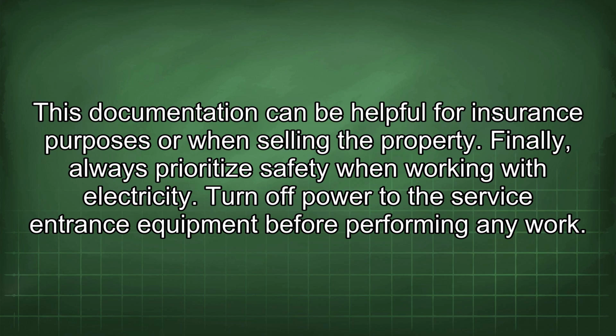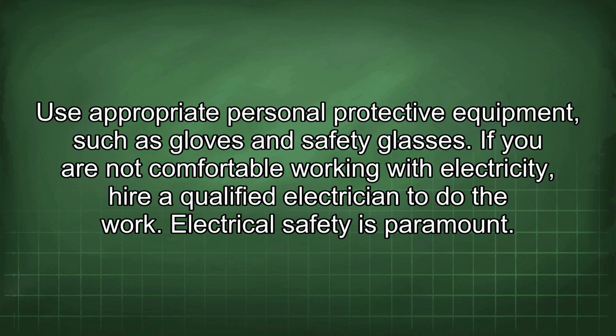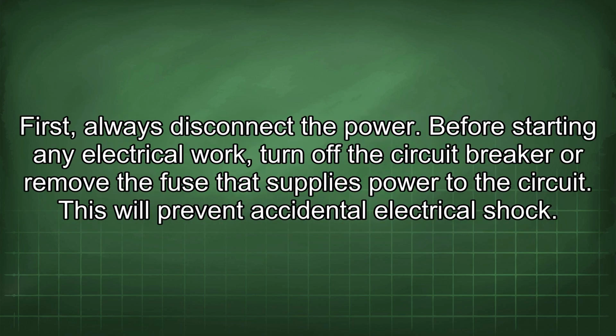Finally, always prioritize safety when working with electricity. Turn off power to the service entrance equipment before performing any work. Use appropriate personal protective equipment, such as gloves and safety glasses. If you are not comfortable working with electricity, hire a qualified electrician to do the work. Electrical safety is paramount. First, always disconnect the power. Before starting any electrical work, turn off the circuit breaker or remove the fuse that supplies power to the circuits. This will prevent accidental electrical shock.